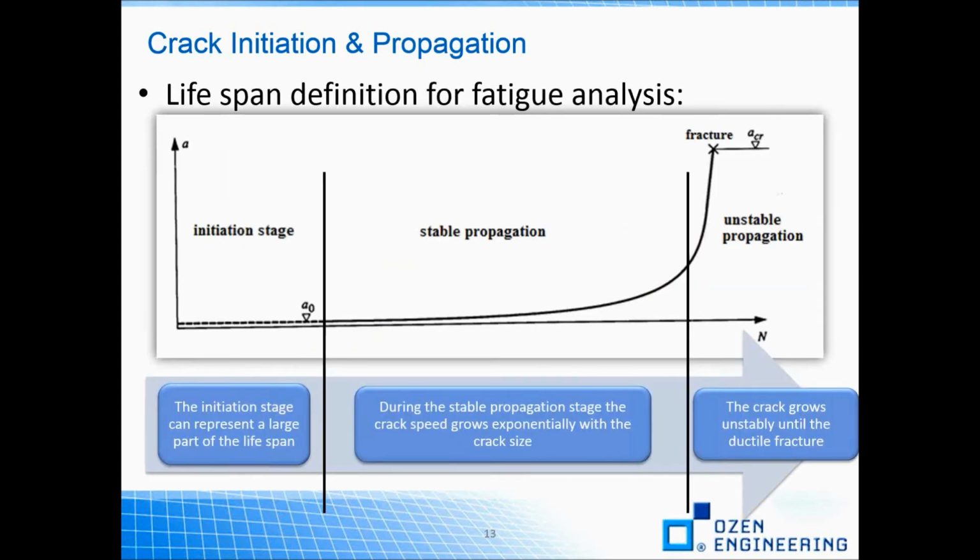So it is generally accepted that in general fatigue cracks start following the nucleation of a crack on a persistent slip band, which is really part of this initiation stage. As we see here in this graph, it's again this a versus N graph. After crack initiation, there are two stages of stable crack propagation before a third unstable growth causes failure.